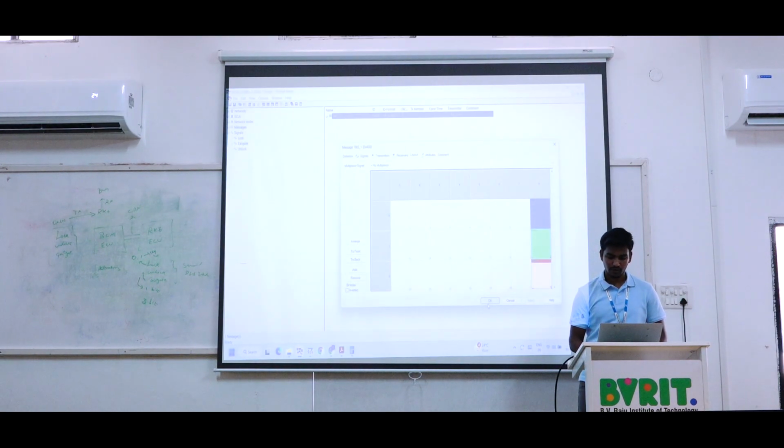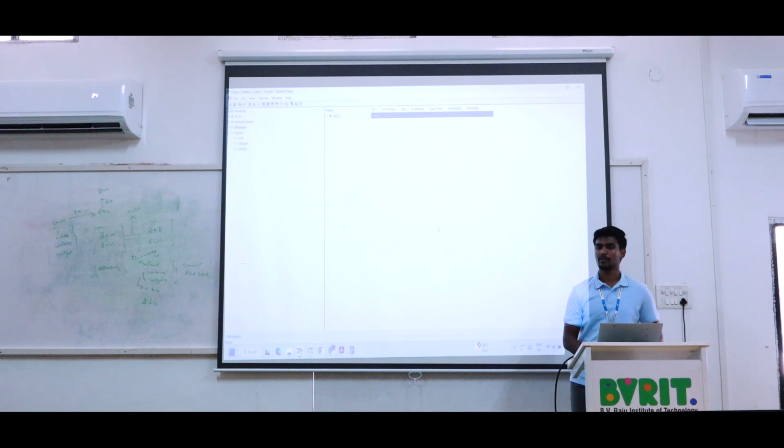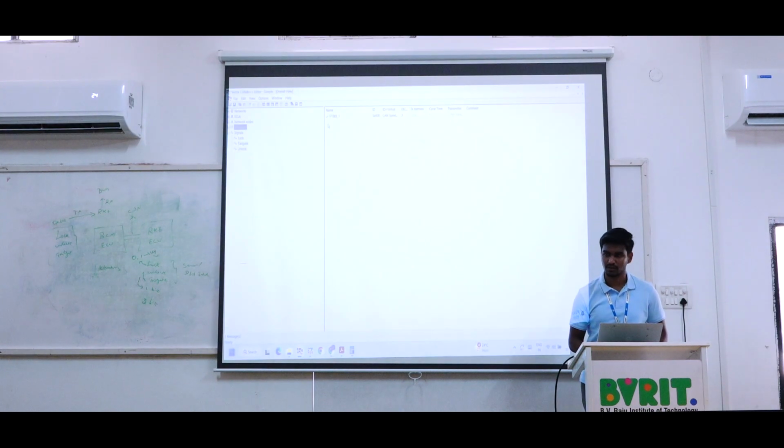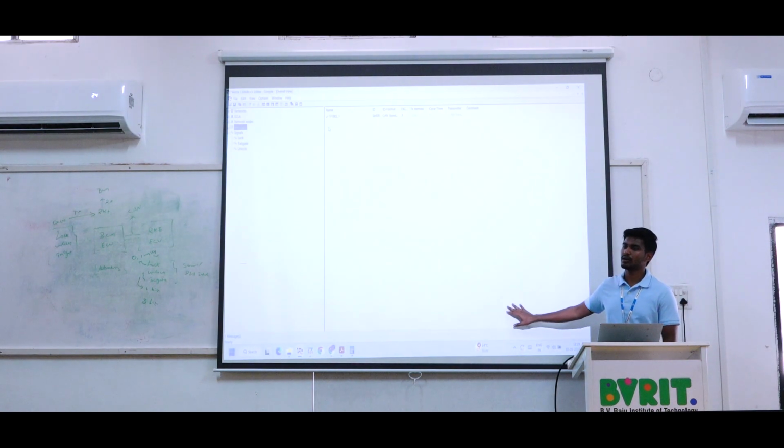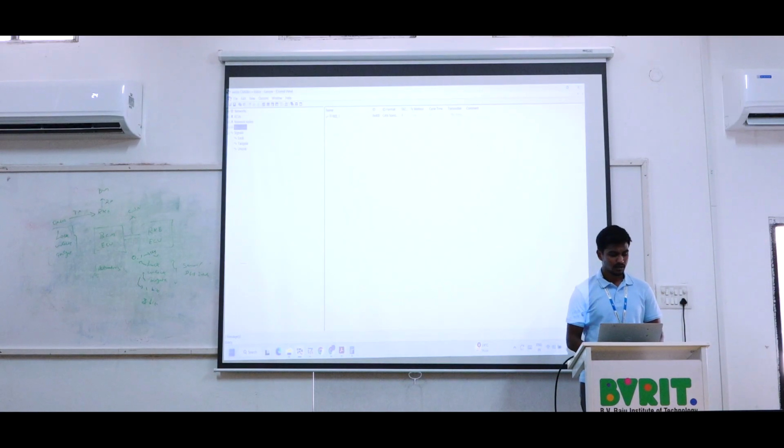Okay. So as of now we have created the signals and we have mapped them by the ID number 400. Finally, you can see here on the signal side we are not getting any X mark because we mapped the signals with the ID number 400 or any other IDs. But the message is still getting the X mark. It says there is no sender node and no receiver node. If you clear this, that will also be resolved.